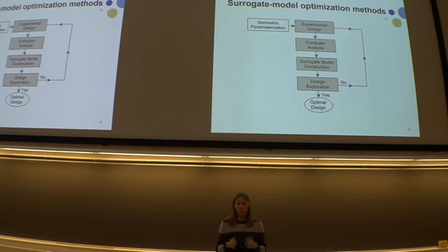parameterize a draft tube in terms of different parameters describing the geometry. Then you choose some different operation points for flow rate and as well for the parameters where you are going to do some CFD analysis. And then you will obtain some results. The whole clue about surrogate optimization methods is to create a mathematical function which is describing how parameters such as the pressure recovery factor and the energy loss coefficients are varying for different design variables.